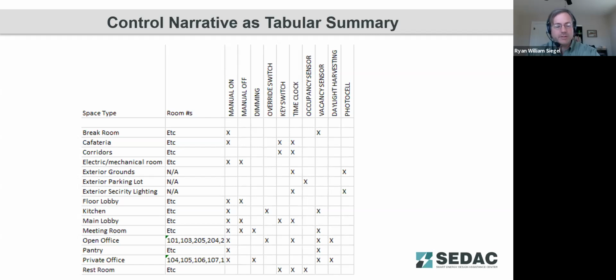And also as part of this, Sean mentioned earlier, there is a threshold for daylight harvesting controls, which if you are able to get below that threshold, commonly 0.6 watts per square foot or less, then you can eliminate the need to buy, purchase, install, commission, and maintain those daylight harvesting controls. So being able to drive your watts per square foot down and installing a more efficient lighting system can also help simplify some of the work for you.